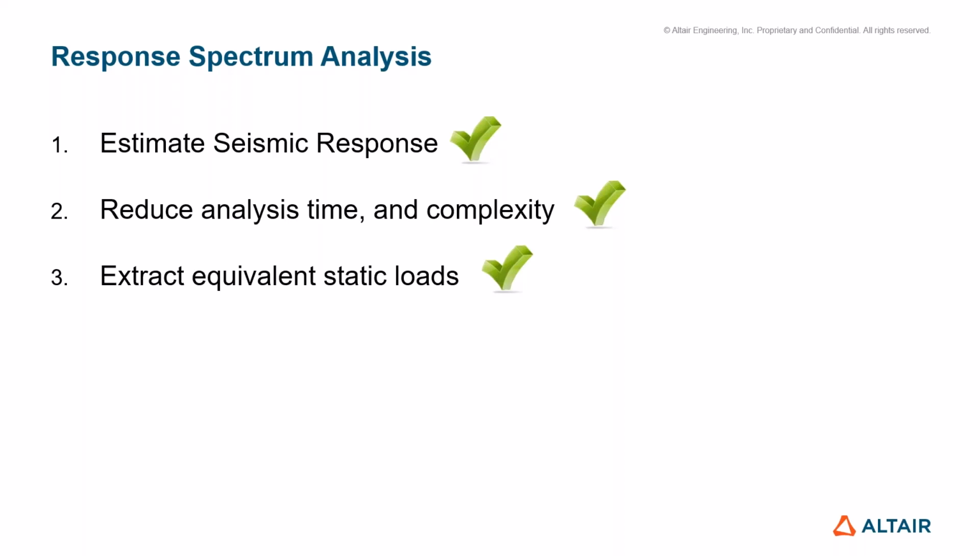If you have a larger model, that can certainly make a bigger difference in terms of how long the analysis takes to run. The one that Tyann was showing, I would say, is of medium size, although using rigid diaphragms does reduce the number of degrees of freedom. And so that makes things a little bit less complicated to not only run the analysis, but also to troubleshoot the results. And it's not too hard for us to then extract those equivalent static loads and perform further analysis or design checks on the model with those extracted loads, if that's something we wanted to do.